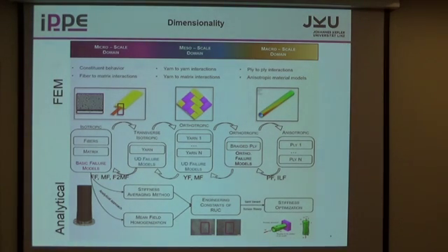We had two approaches. One analytical approach, which started at a microscale level. We started developing a model of carbon fibers interacting with matrix, which we extrapolated by mean field homogenization to the behavior of a representative unit cell in that braided material. And as soon as we knew the mechanical properties of that representative unit cell, we could basically determine what's happening in the final braided composite. That was the method that we developed for the industry. It takes about 1 minute to solve. It was written in Mathematica, a bit more details here.